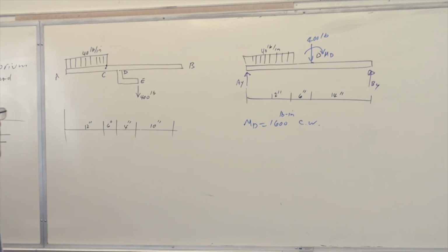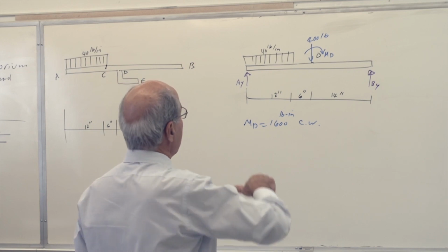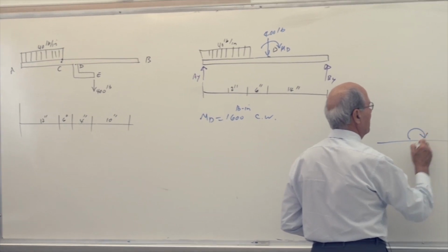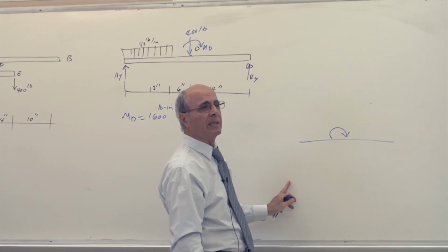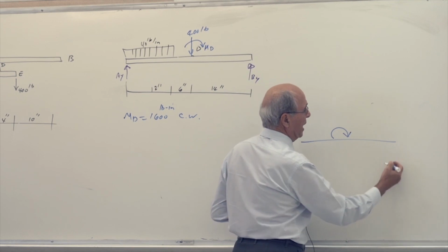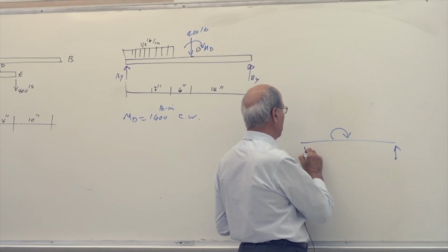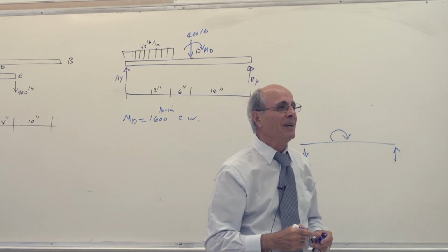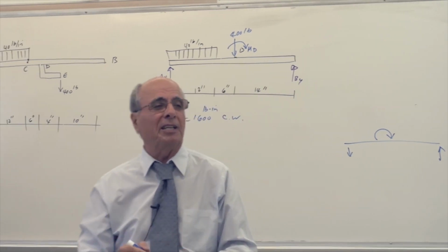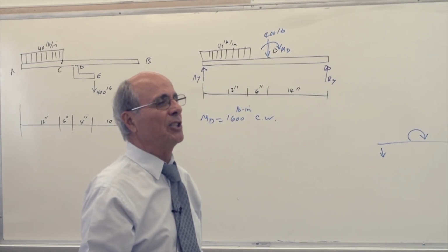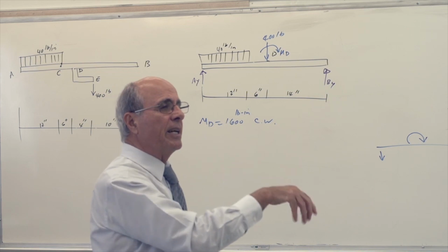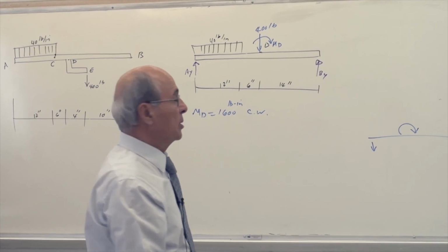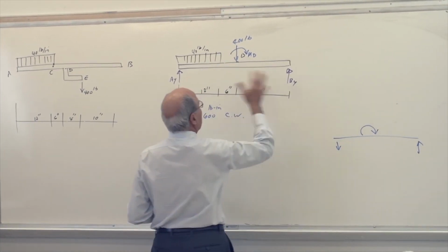So M comes into your picture and affects your equations; in other words, M pushes this one. I want you to understand this. If there is a beam like that and there is a moment like that, people think there is no reaction here and there. If this one actually pushes down, you have a reaction here going that way, but this one will be a reaction this way because it wants to go up. These two are equal, and because they don't see any force, they think there is no reaction. That's their idea. Is that understood? So a moment creates a reaction on both sides, equal and opposite. If this moment was not there, the reaction would have been different.